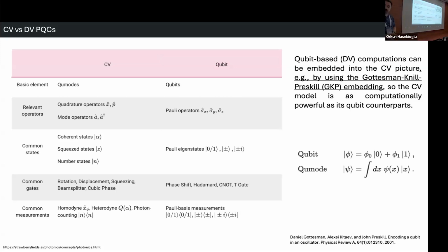And for the measurement methods, for single photon states, for discrete variable, you need single photon detectors. Like I said, you need to cool them down. They are extremely expensive, but for the continuous variable system, you just use regular photodiodes. But you should check the frequency response of these photodiodes.